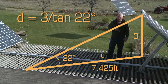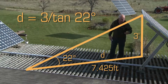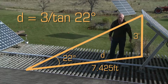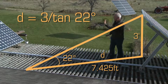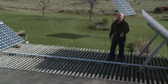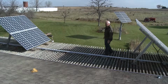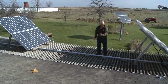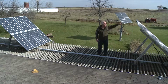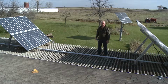Now, that though is the distance from here to here off at a 45-degree angle. It's not the distance straight back to the next subarray. If we were to just use that 7+ feet, that would be back much further than it would absolutely need to be. So we have a second triangle that we need to do a calculation for. Here's our second triangle. Our first triangle was vertical. Our second triangle is going to be flat on the floor. It's a horizontal triangle. I'm still using the point where the shadow line comes down to the triangle down here.